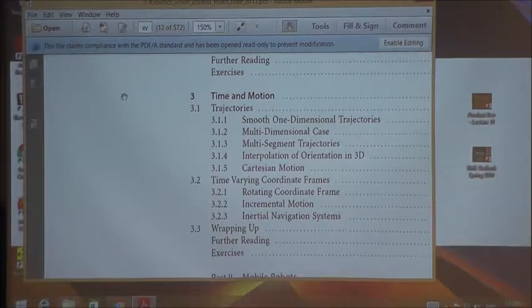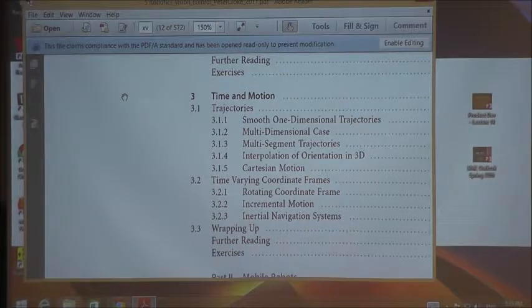Okay? You do your design based on a linear model, but you don't throw away the nonlinear model. You bring your controller, close the loop around the nonlinear system, and test the validity of your design. A lot of times it's good enough, but sometimes you may be pushing the system into a region where the linear model is no longer valid.